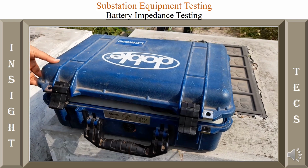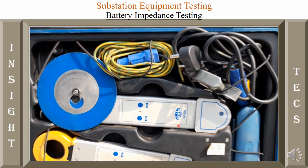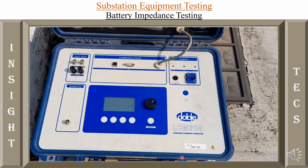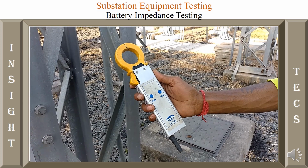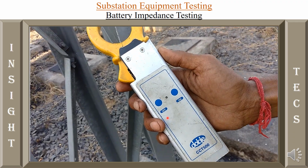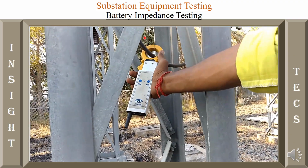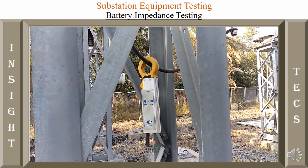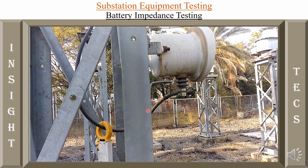So friends, this is how the LCM kit looks. It has two probes, the clip-on meter and the FP500 disc probe. This is a basic LCM kit packaging, how it comes. We will put the clip-on meter on the cable that is connecting the LA and the LA counter. We have turned it on, and now we will hang this clip-on meter on this cable. It has a provision for an antenna over here through which it will be connected to our testing kit. See, it is connected on this cable.